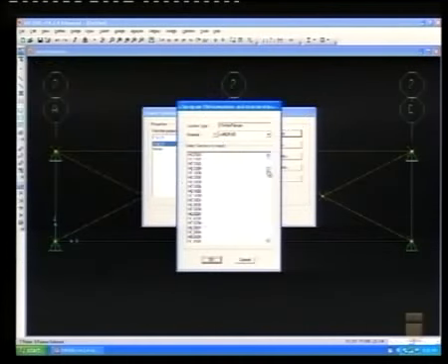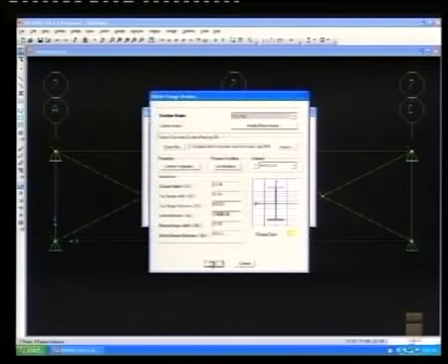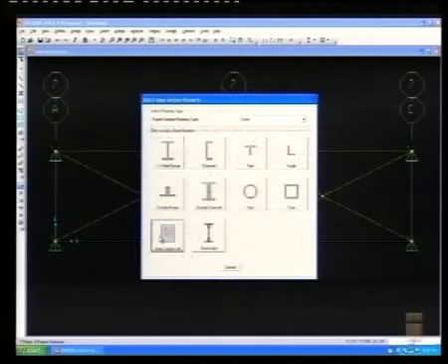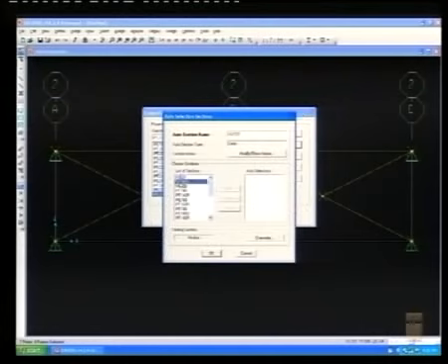Now you can take all IPE sections, but from my experience, IPE, because the load is small, will not exceed the 240. But let me go up to 270. Okay. Here is okay. And here add new property. We want an auto select list of all IPE selected.